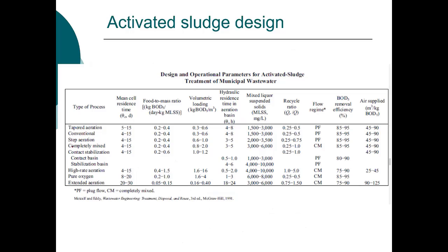We will focus our discussion here on completely mixed reactors. So notice here, typically you're looking at about 4 to 15 days that the microorganisms are being recycled. We talk about a food to mass ratio. So that is the mass of BOD per mass of MLSS, mixed liquor suspended solids.